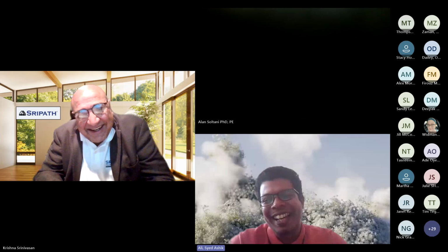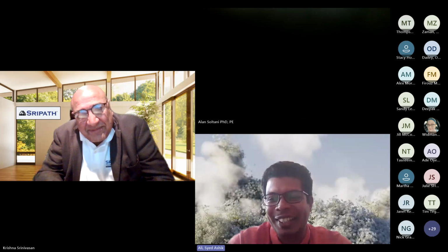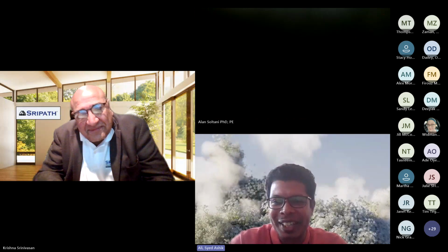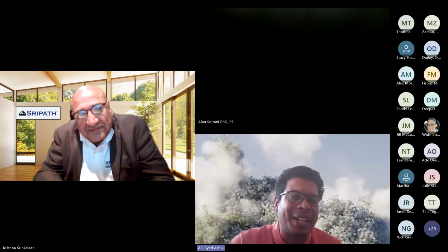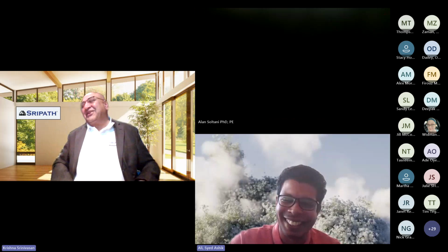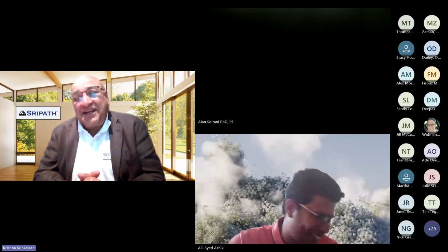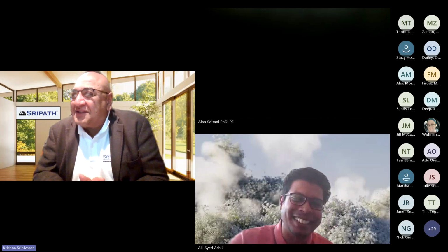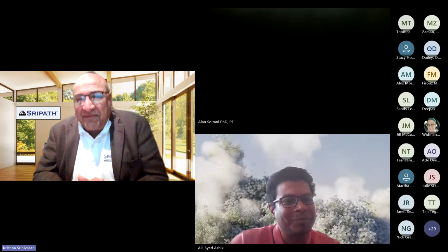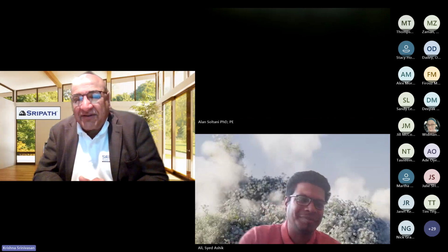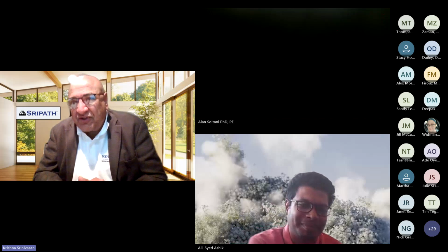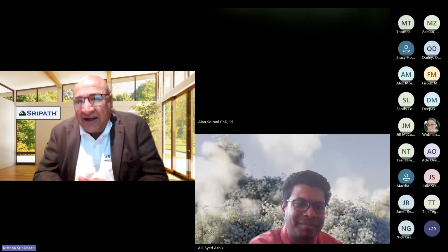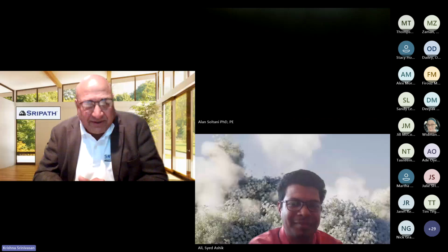Okay, sure. How many? So this is a very, I think, tough question as well. How many times can we recycle a RAP with rejuvenator? Very good question. We have some data. I didn't have a chance to go through this. Clearly, if you take the same mix and recycle with the same amount of rejuvenator again and again and again, clearly there is some drop off in performance.